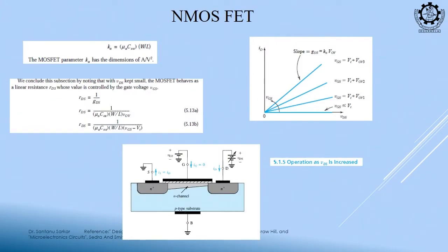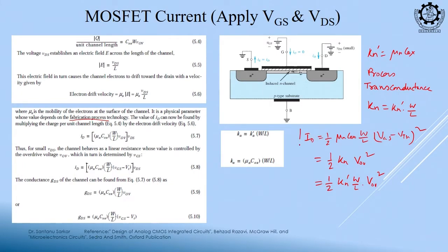So, let us try to understand how this current is formed. Now, from this value, can you tell me, does this current depend on VDS? Is there any expression of VDS? No. So, it should be constant, right. So, when it reaches a certain value, it is independent of VDS, right. So, in this region it is dependent on VDS. The moment it reaches the saturation region, you see this is constant, because in this equation there is no VDS, and this region it is like this.